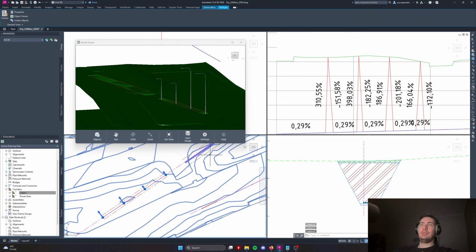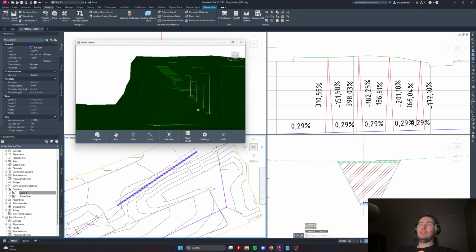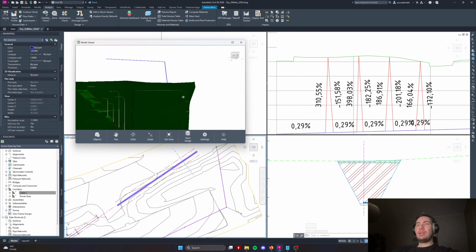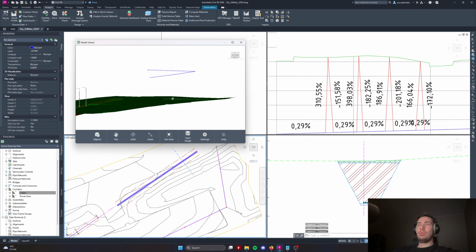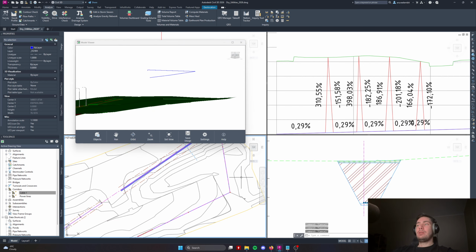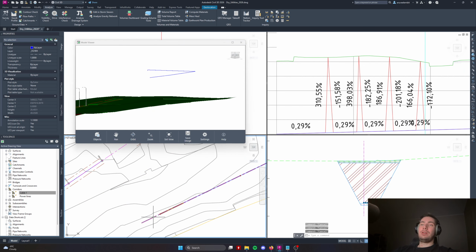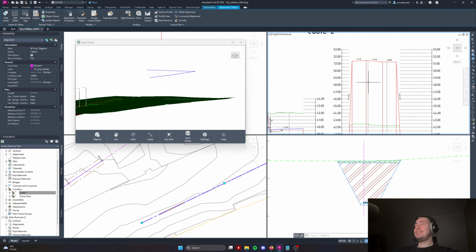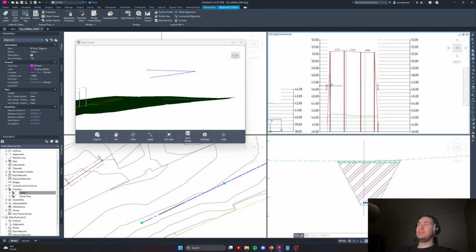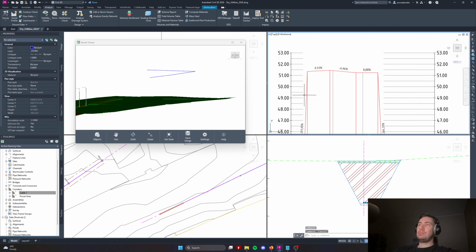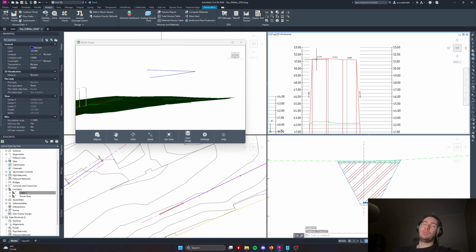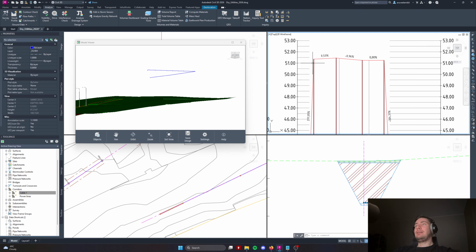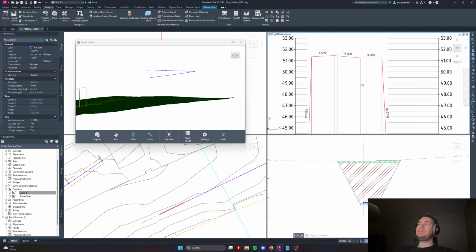And yeah, right here we have the TriNetworks utilities. But yeah, let's get back to the power lines. So the power lines, right? For the power lines, I have an alignment as well, which has the name of cable 2, and I have a profile for it as well. For instance, I want to have it on a specific height. I create a profile for that height.